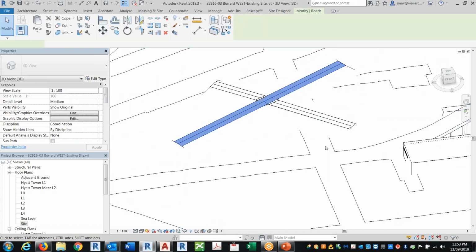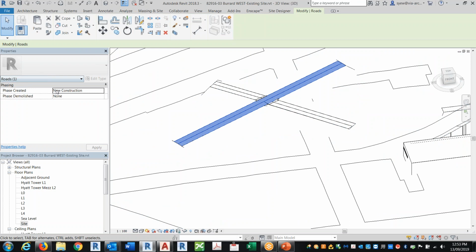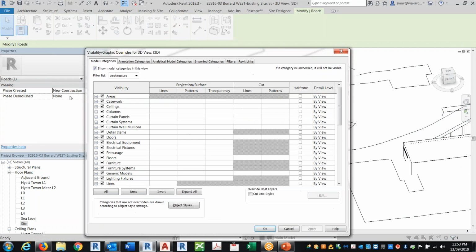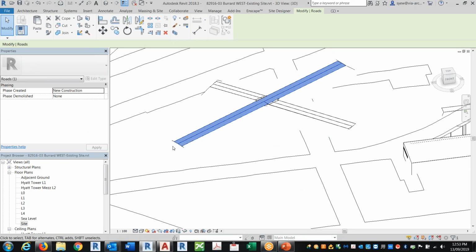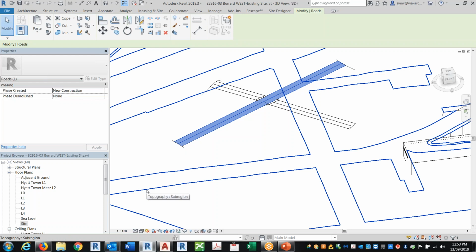But one thing it does is that it creates what's known as the road parameter. Because in here, you notice that there is one called road. You can never create it using a real Revit family. So this is where that category comes into play. People always ask, why do we need road? Yeah, it's because of the site tool. Unfortunately, it's not very useful. You see that there's nothing here I could adjust. So it's pretty much dead on arrival. If you can't modify this, it's not very useful, then what's the point, right? But just play around.